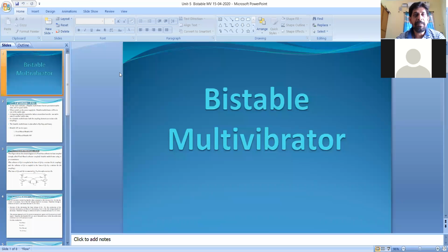Why? Because the voltage applied at the base of the transistor through R1 and R2 changes the voltage. Then the charging voltage of the capacitor also changes. That's why it is also called a voltage to frequency converter. General applications are used for generating square waves.